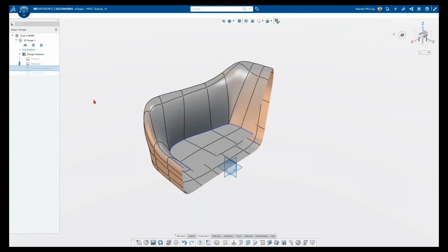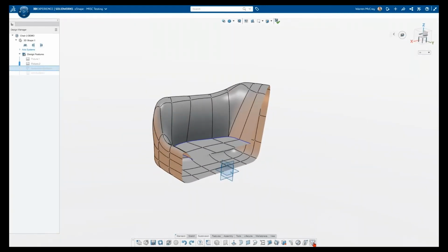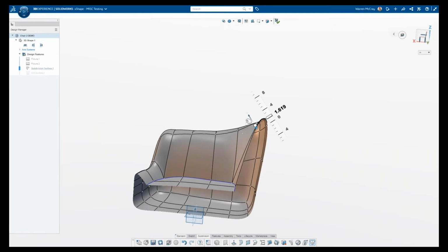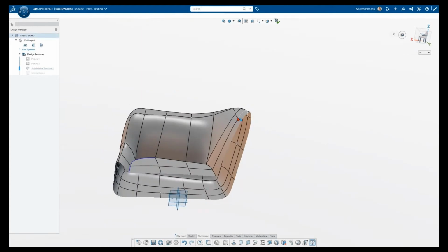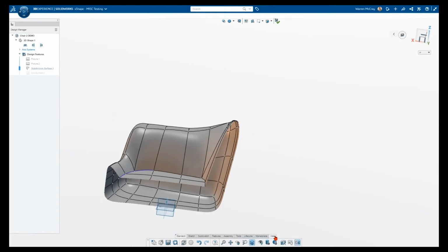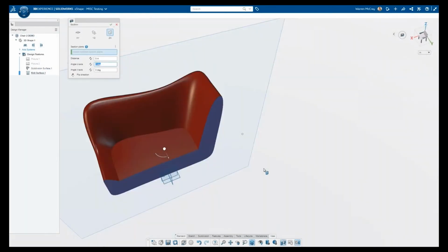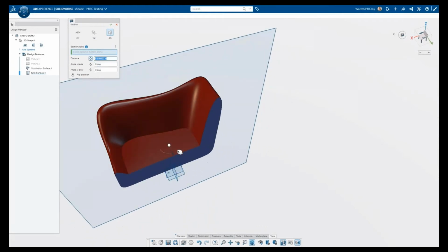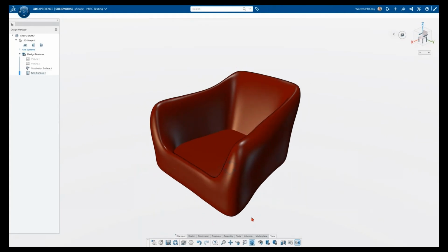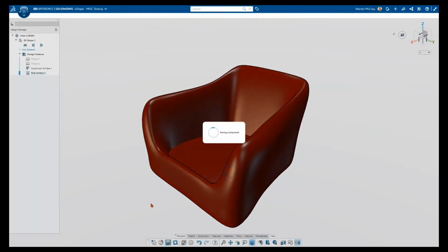So now this is what I thought was great to show you guys. You can create a section view, and then look at just the surfaces. Then you can right click on a robot and change the orientation of the robot to either XYZ coordinates, or delta X, delta Y, delta Z, or normal to an edge or normal to a surface. And you can actually pull the surface yourself and watch how the surface moves in the section view. So it's not just a section view you can look at, but you can actually work on a model while it's sectioned.